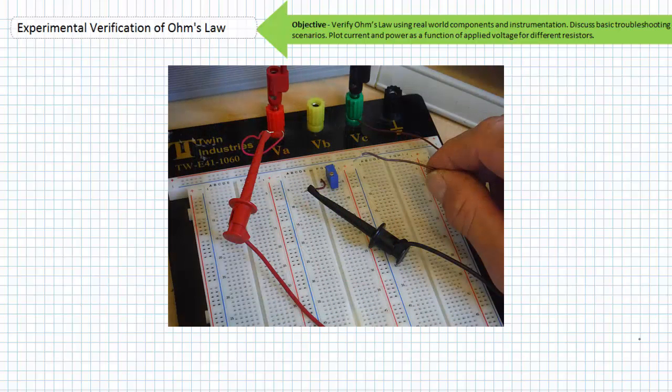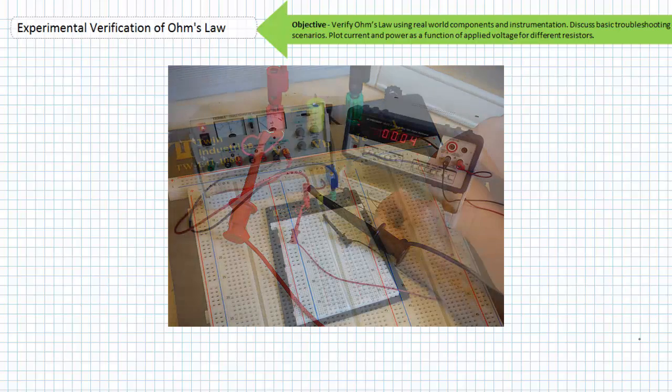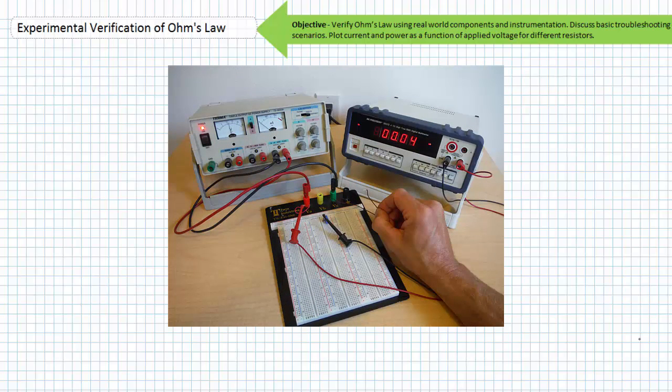Here's a close-up of the return wire removed from our circuit with the ammeter inserted. Remember, protoboards are temporary circuit building environments, and just by accidentally wiggling this wire, it could pop out of the connection point. Be gentle and handle appropriately. With this single wire removed, the current indicated by our ammeter instantly drops to 0 milliamperes because a complete circuit no longer exists. Now is the time to get up close and personal with this protoboard. Scan it and see if you can find a wire just dangling out in space. Don't think it's going to be this obvious though. Most likely it'll just be subtly out of place and it'll be up to your attention to detail to notice this.